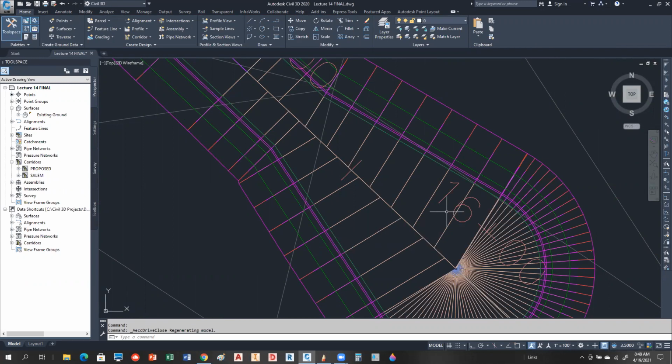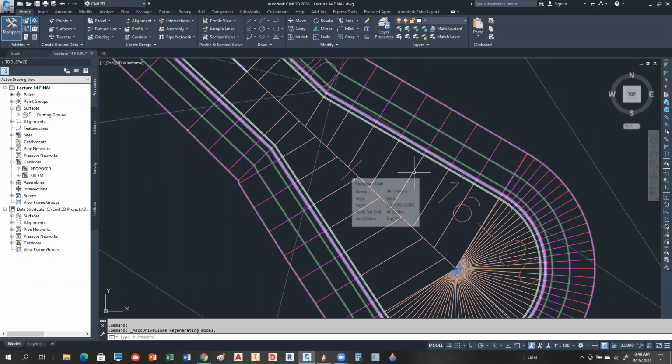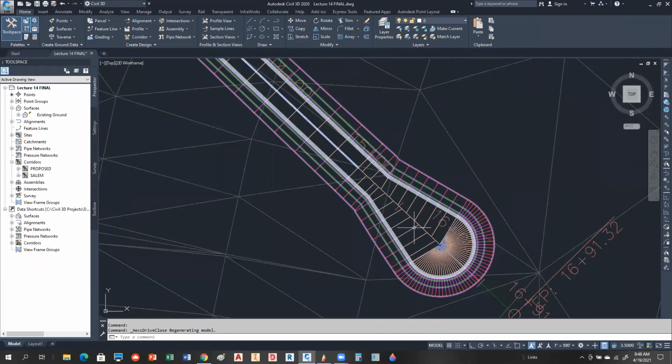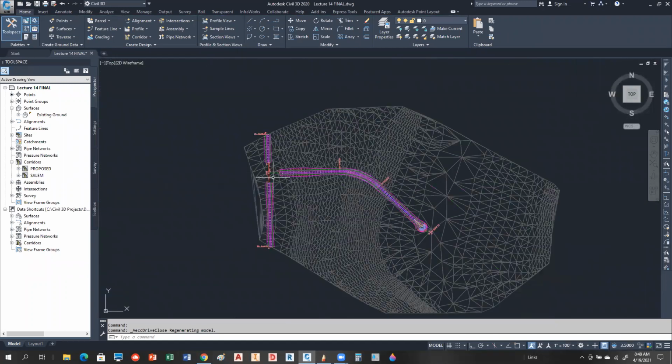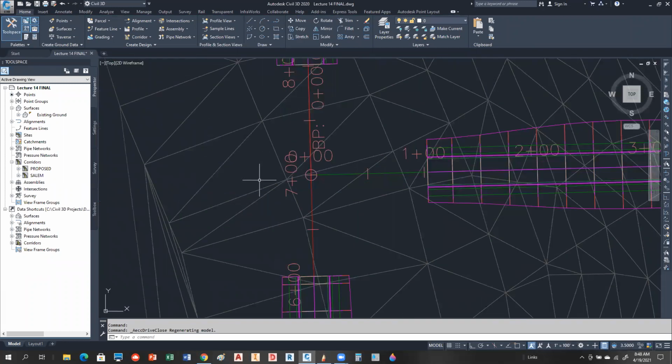And if you wanted to get a little bit more frequency in here, you could set your tangents down to like 2s or 1s, even 2. So it does make a difference in how many points you're getting. But remember, the more points you have on that frequency, the more templates or sub-assemblies, the bigger that file gets overall. So, okay. Is everybody good with this so far? Pretty impressive, isn't it?